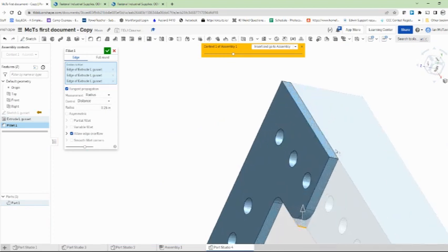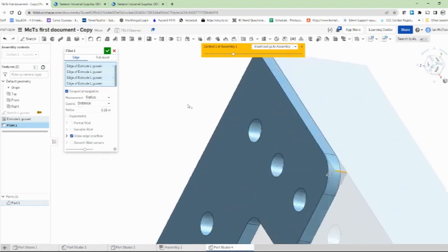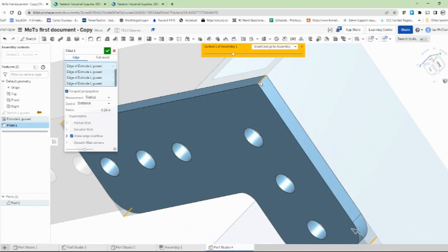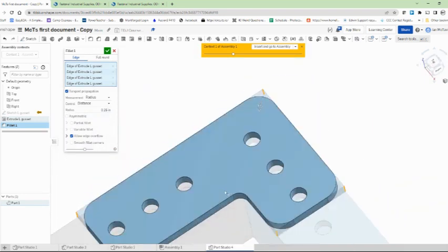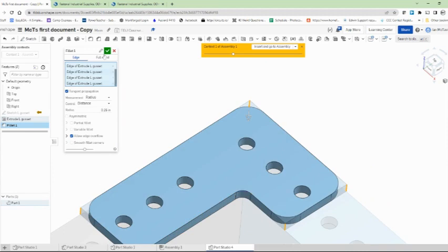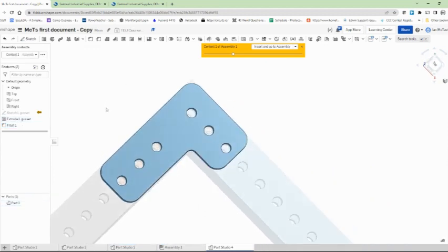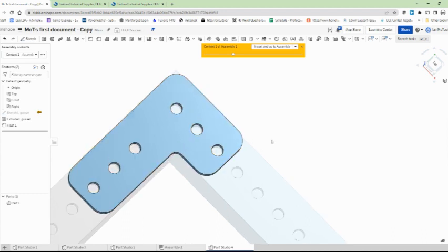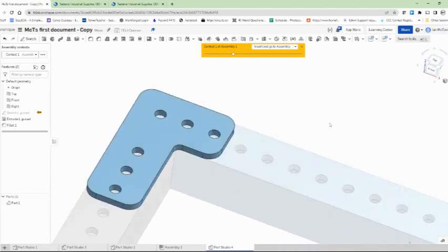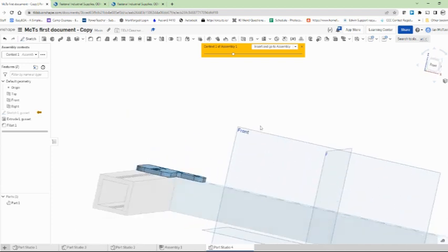And the benefit of that, cutting this on the router, is really easy because it just goes around. It's the inner corners that are tricky, because you've got to make sure that everything will fit. But that now doesn't have any sharp edges. That's the other benefit, is with metal, by rounding it over, you're reducing the sharp edges, and it doesn't have any points of failure. If we were to bang on this, the force would be distributed around the curve instead of around a single point. So there's an L gusset.